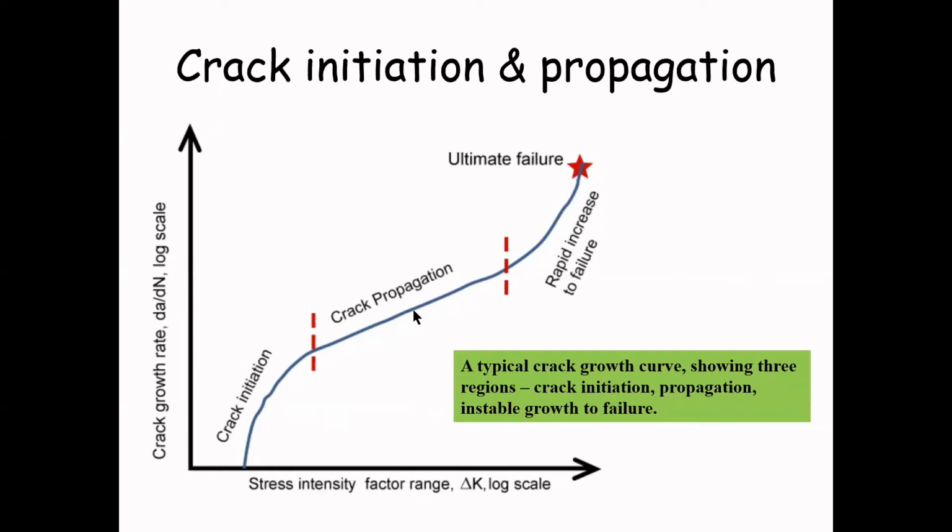Notice that the crack initially grows very slowly at this phase. And we can see the growth accelerates as the crack size increases. The reason for this acceleration in growth is that the growth rate is dependent on the stress intensity at the crack tip. And the stress intensity factor is dependent on the crack size, a. As the crack grows, the stress intensity factor increases, leading to a faster growth. And the crack grows until it reaches a critical size, and finally failure will occur.